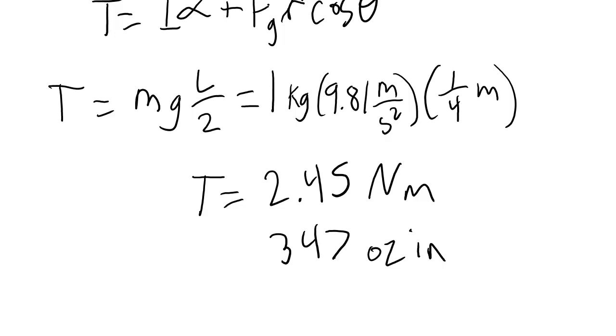However, this explains the reason why the SCARA type manipulator is often used for pick-and-place operations. The amount of torque required to move links and payloads in a direction that is perpendicular to gravity is much less than the amount of torque required to move objects in a direction that is parallel to gravity.